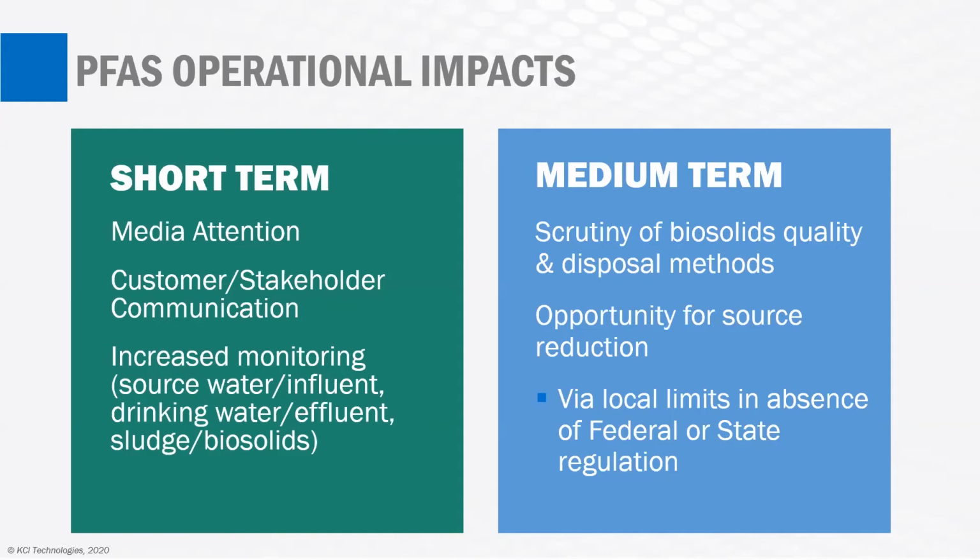Moving out to a 3 to 5 to 10 year frame, what I'm calling the medium term, I think there's going to be more scrutiny of biosolids quality and the disposal methods. In other words, they're going to start looking at the wastewater treatment plants, the POTWs, and what's happening to those biosolids. We have Class A biosolids going to public distribution, maybe some Class Bs going to land application. And what if we have PFAS in there? People are going to start looking a lot closer and saying, okay, is this becoming a major route of PFAS to get into the environment?